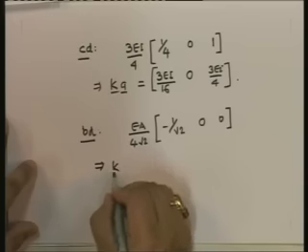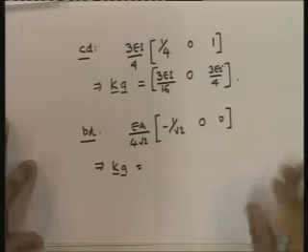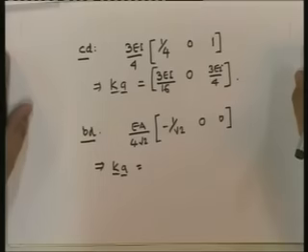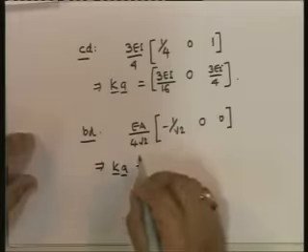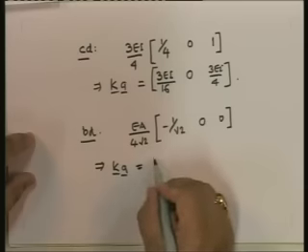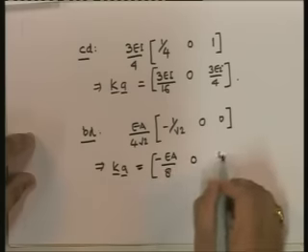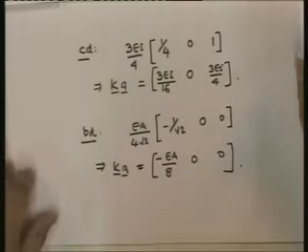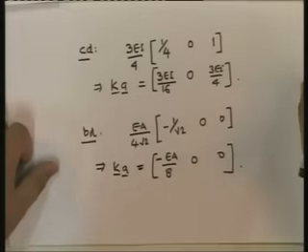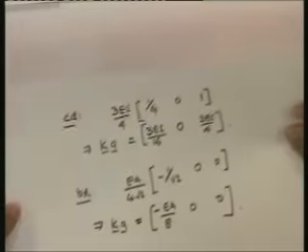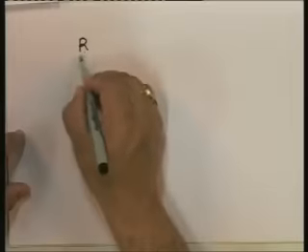So this implies KA. Note that whether it is a flexural member or an axial member, the concept is still the same. Only thing is here we have EA. So if I look at it, this becomes minus EA upon 8, 0, 0. Okay? And we know the values of EI and EA, so we can plug those in. So now, once we have that, then ultimately we have this.